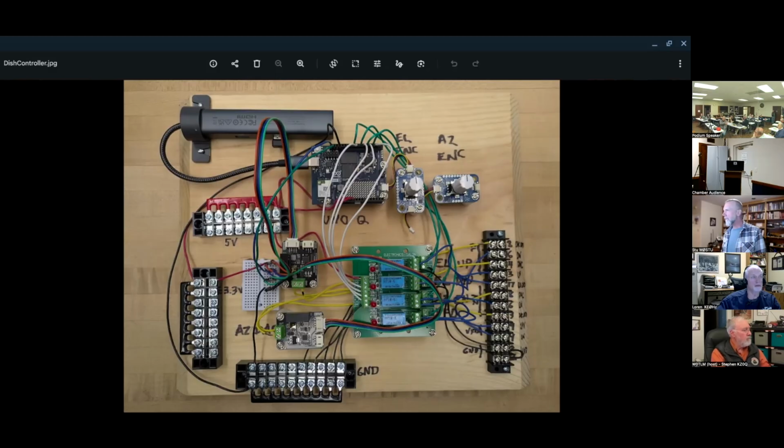So we use what one of our folks in the organization calls bang bang positioning. We let the thing drift off till it's about 3 dB down, and then we move the whole dish to a new position that's 3 dB down, but it leads it, so it then drifts into 0 dB down and then across to minus 3 dB down. So the antenna actually stays stationary for quite a bit of time and then moves, because there's an awful lot of wear and tear on taking the brakes off and starting the motors up and all of that. So we try to move the dish as little as possible while we're tracking.